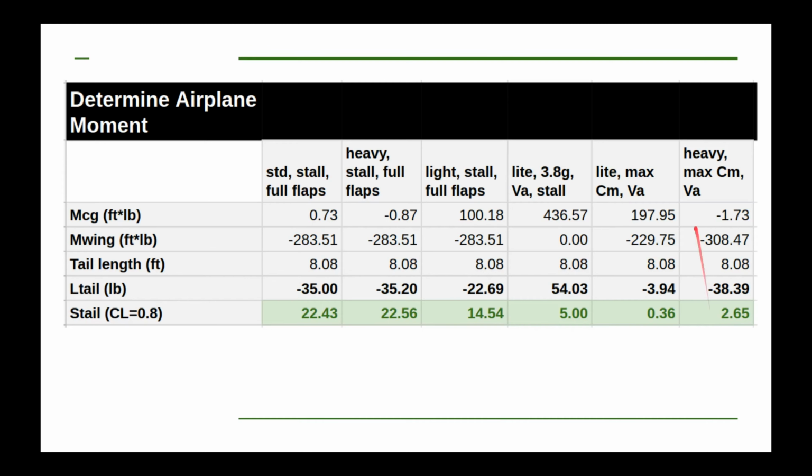Well, remember, our speed is our maneuvering speed. That's up around somewhere in the low 70 knot range. Our stall speed, though, is at 24 knots. When you're increasing your speed, your flying surfaces become more effective by the square of the velocity. So this velocity here is way, way more than this.